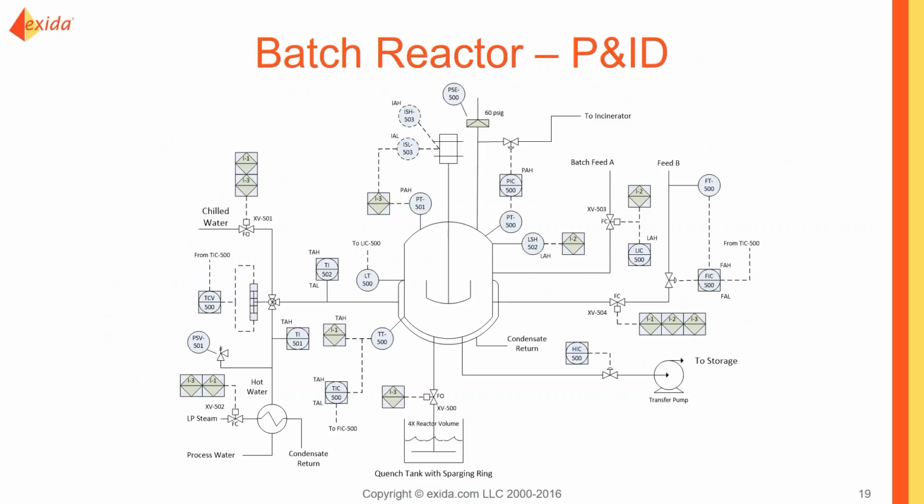We do have a P&ID here. This is going to be your starting point, your process design. You can analyze this to see if the safeguards needed are in place. We do have a little bit to work with here. You can see we have a few interlocks, a few alarms already in place. We have an interlock that responds to temperature, an interlock that responds to high pressure, and an interlock that responds to the level going too high. There are also some simple process control loops.